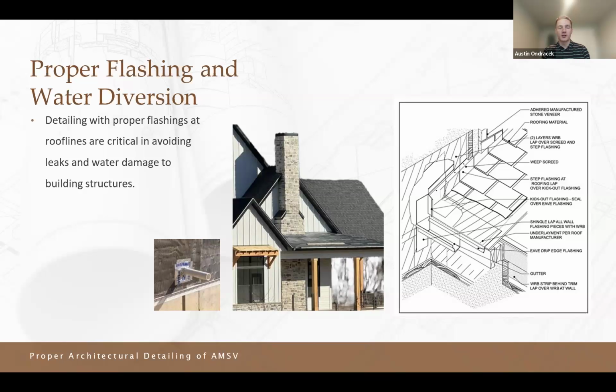Talking about a rain screen funnel, if you haven't seen a video of how it's done, I highly recommend looking at it. It's a very unique process of just channeling that water between the substrate and the stone and having it pop out at the bottom at that weep screed. And it works great. It's just a great best practice to make sure that even if there is water that gets behind the product or the manufactured stone, it's not going to cause any issues to its actual adhesion to the substrate.